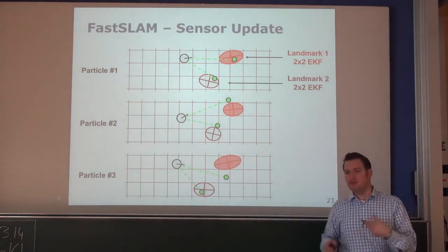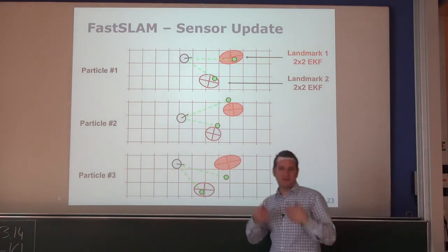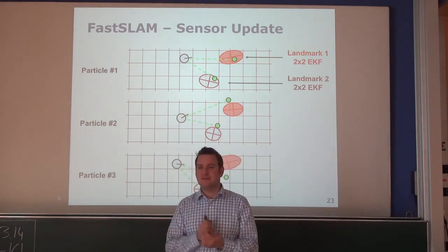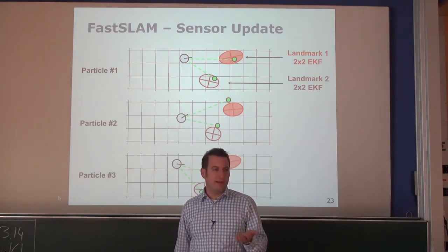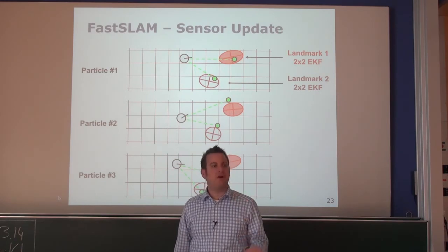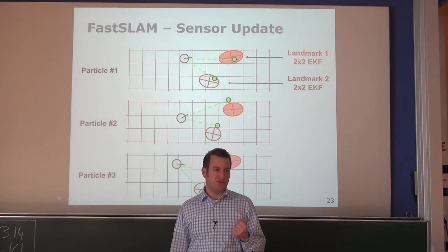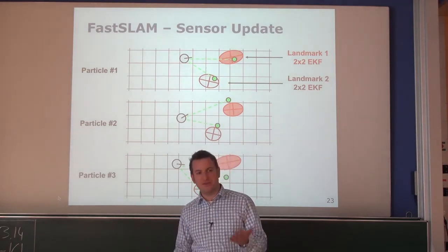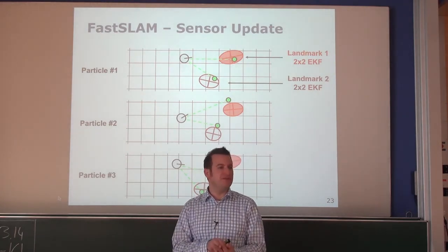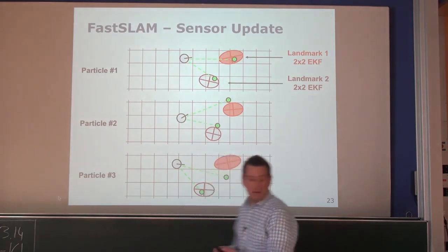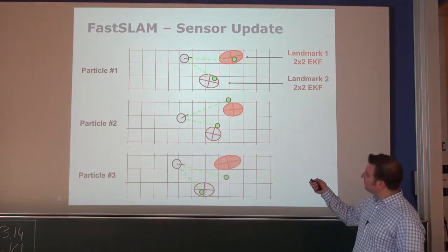But if I talk quite informally about that, it's kind of an evaluation: how well did the particle estimate the map given the current sensor observations? So how well are the current sensor observations in line with the map that this individual particle built? If you think about over here, that actually looks pretty close.